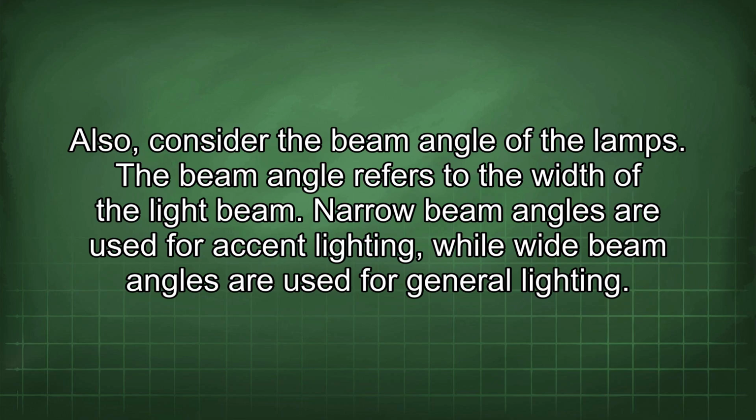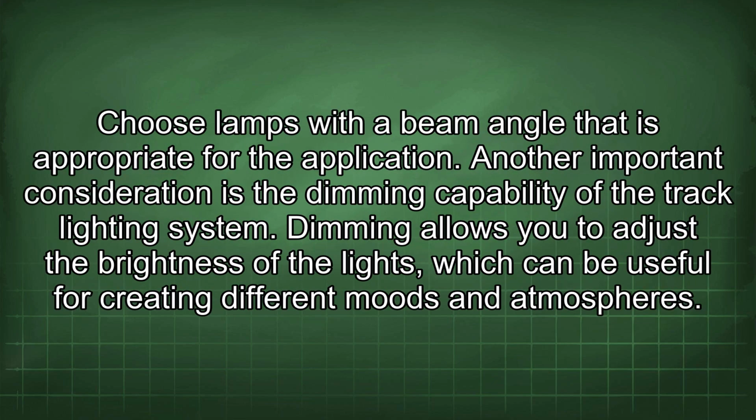Also, consider the beam angle of the lamps. The beam angle refers to the width of the light beam. Narrow beam angles are used for accent lighting, while wide beam angles are used for general lighting. Choose lamps with a beam angle that is appropriate for the application.